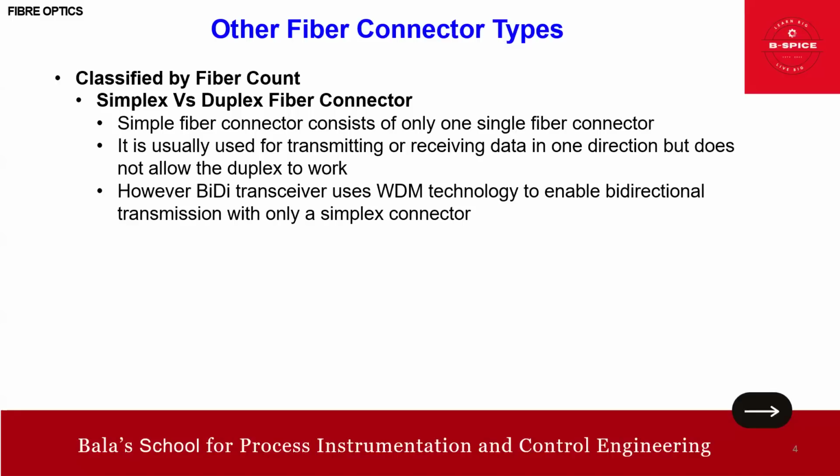However, we have a BiDi. What is this BiDi? It's basically a bidirectional transceiver which uses WDM technology, wavelength division multiplexing. This technology enables bidirectional transmission with only a simplex connector. There are many advantages on this aspect, but it is beyond our topic of discussion. Basically, it uses a different wavelength for sending and receiving, thereby allowing efficient bidirectional communication on a single fiber.